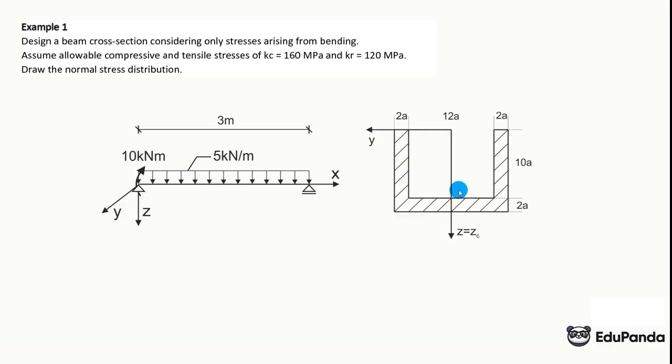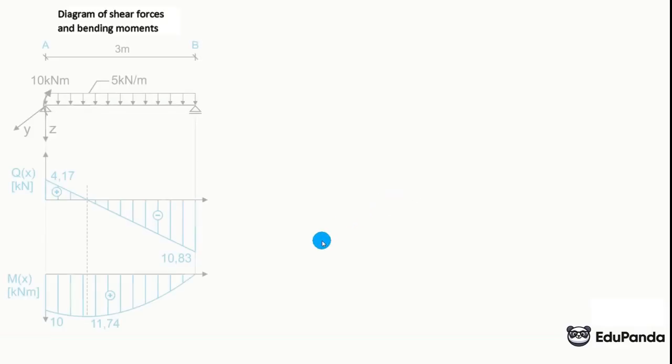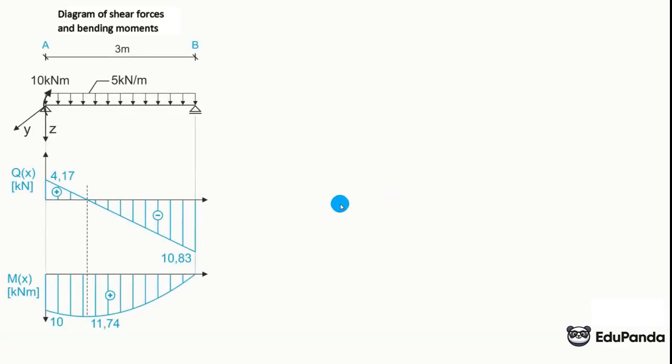So the symmetry axis is always the central axis, so here we have one axis, and the other axis is random, because it needs to be shifted to the center of gravity. And now I have also adopted a right-handed system, but the horizontal axis goes to the left, and the vertical axis goes down. In the previous video, the horizontal axis goes right, and the vertical axis goes down. That is also a right-handed system. Just like this one. It's important that the system is right-handed.